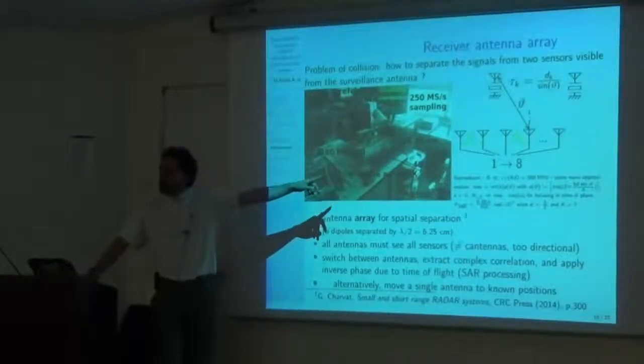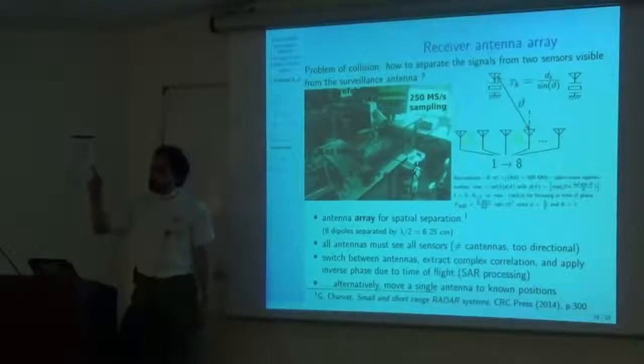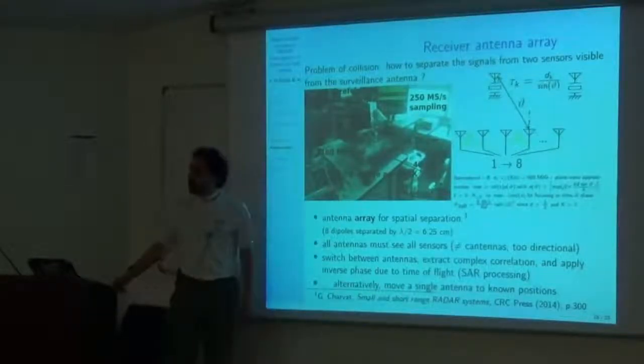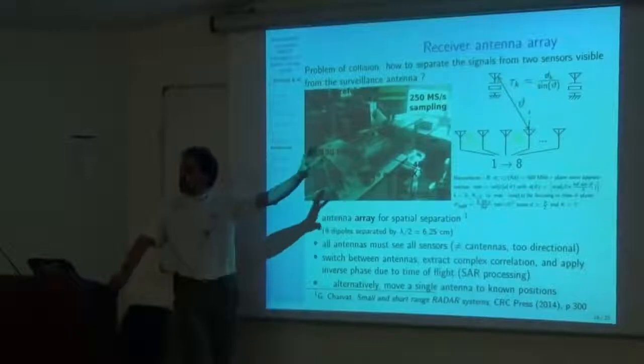This is still Ethernet, but I still need to initiate all the transactions between the PC and the oscilloscope and get all the data. I believe that if I use the direct memory access block that Gwen wrote for me for the Red Pitaya, collecting the data from the FPGA of the Red Pitaya and sending it through the DMA to the CPU, then I will save a lot of time compared to transferring from the oscilloscope to the PC. But indeed, you're correct, I assume that the environment is static during the whole measurement.